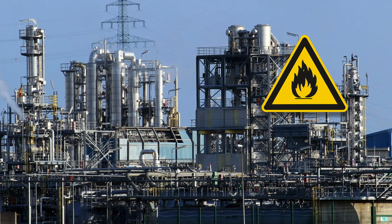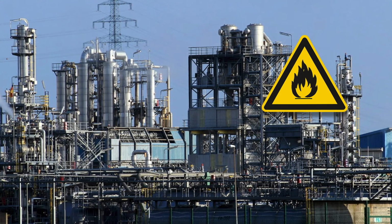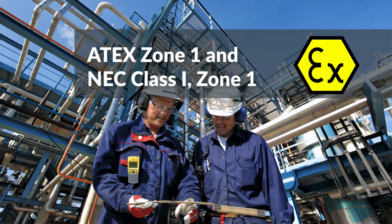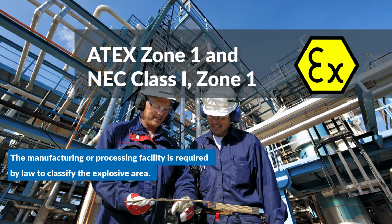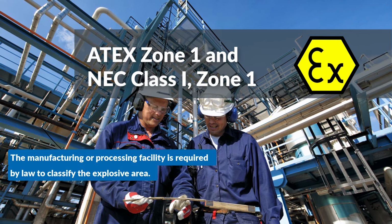Since an HMI is a possible ignition source when used in a hazardous area, consider mounting it in a safe area. If not, the HMI specified must be clearly marked with the certification for use and the area classification. For example, ATEX Zone 1 and NEC Class 1 Zone 1. The manufacturing or processing facility is required by law to classify the explosive area.